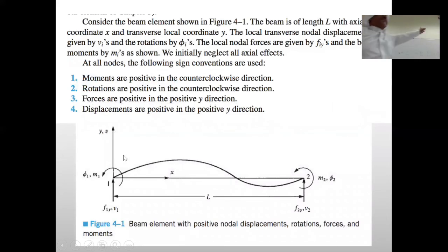That's it. You can see here, this is a beam element, and this is node 1, this is node 2, and in node 1, you can have what? You can have displacement and rotation, and there also displacement and rotation. You can have force, and you can have what? Moment, and you can have force and moment. I think now you can construct your stiffness. You have to relate forces to displacement. Okay, can you tell me what should I write? Vector equal to a matrix times a vector.